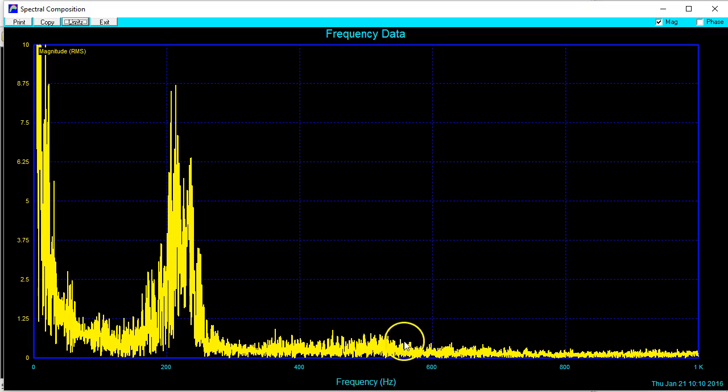And so there's going to be some aliasing from this signal energy if we were sampling at 1 kilohertz, but it's not going to be very substantial. It's going to be relatively weak. And there's so much strong energy already in here that any aliasing artifacts from this stuff, I'm not an expert on this topic. If somebody like Boris disagrees with me, then I will defer. But it feels to me like the strength of this is so weak that it would not have a substantial effect up here.